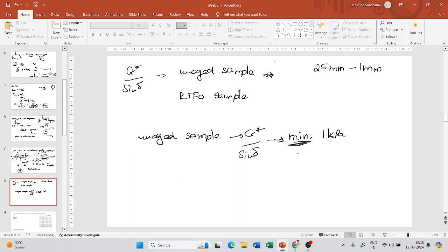Okay, so for our sample, say this is my criteria, and let us say I'm finding out this criteria is satisfied when the temperature of the bitumen is 62.5 degrees Celsius. Now how will you find out the high temperature grade of bitumen?